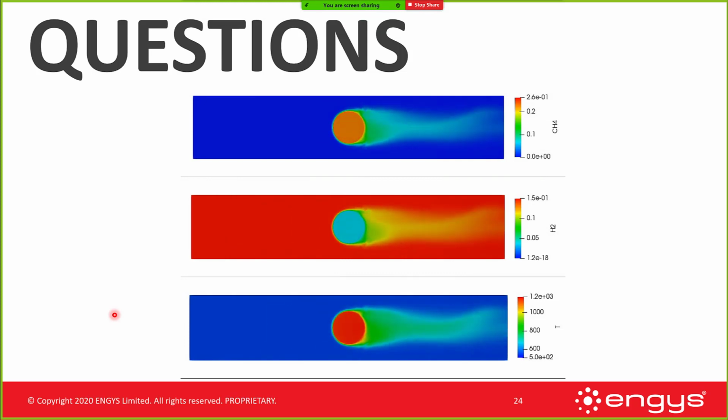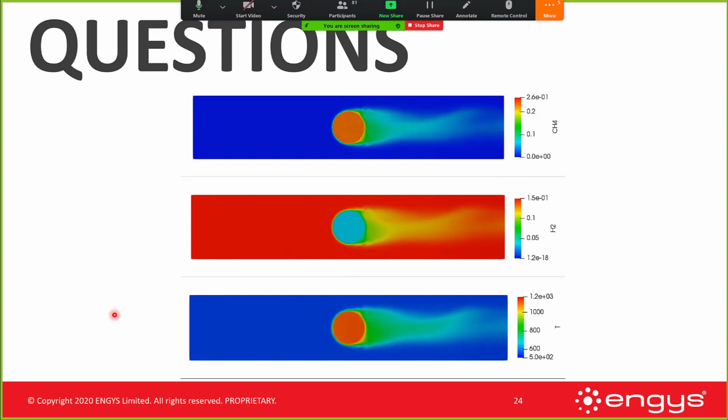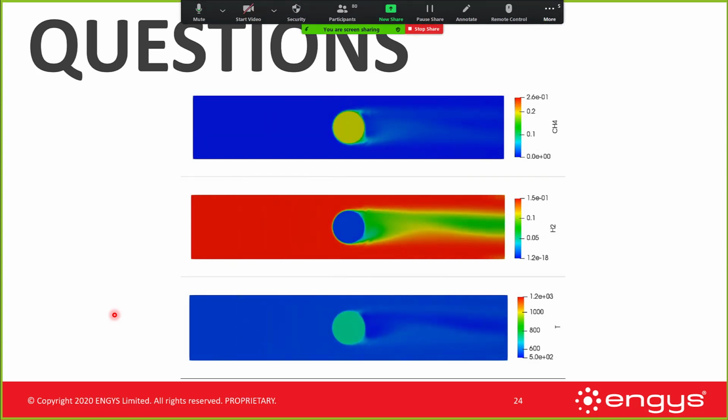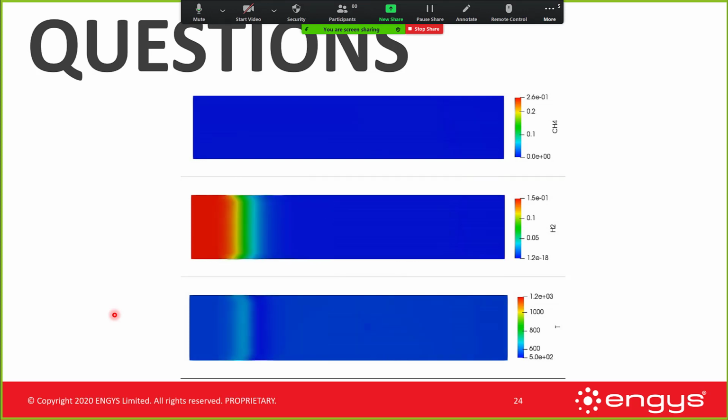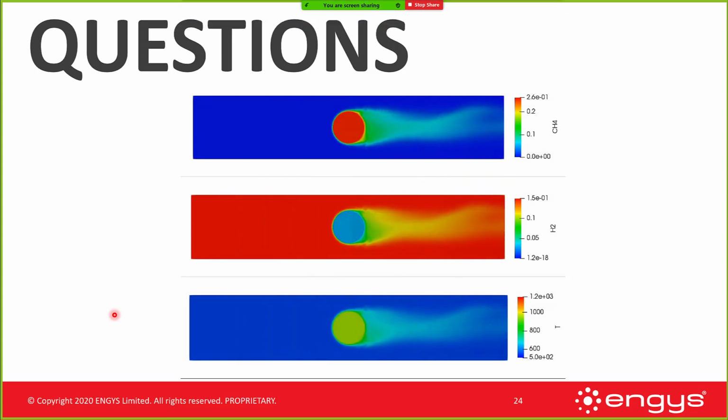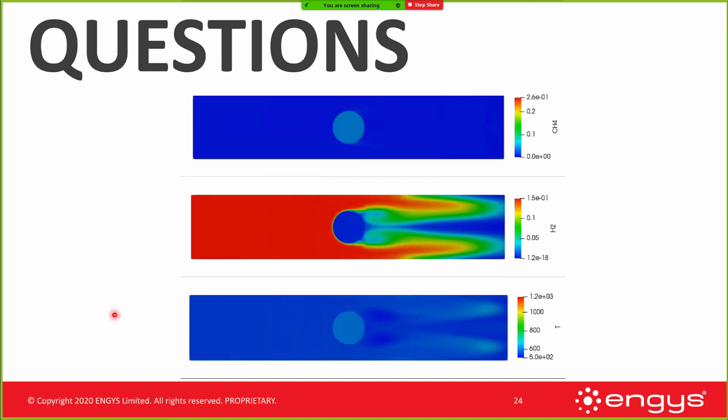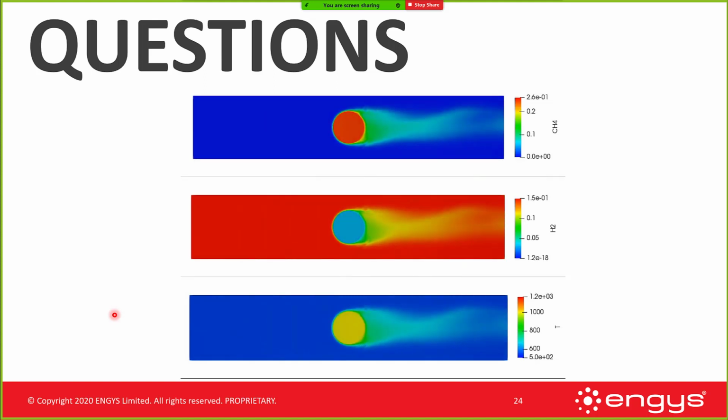And one of the reasons that I haven't really is because then we're moving to transient. Even if we do a pseudo transient with the DES, it doesn't really gain me too much. In fact, it might hurt me. And with DES, we've got vortex shedding off of the particles in such close proximity to each other. I don't know if I would really gain that much more information, and a RANS might still be better for that. But that's a great question too.